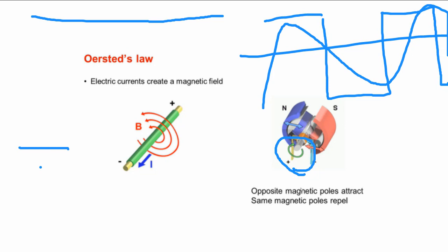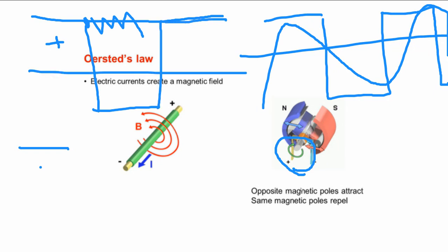So my brush acts as a positive alternance, and at this point, after 180 degrees, it turns to the minus side. This is cancelled. My waveform goes to the minus alternance, like this one. This is like a sinusoidal operation.